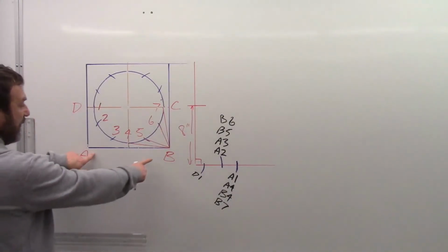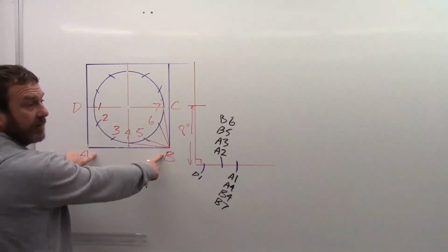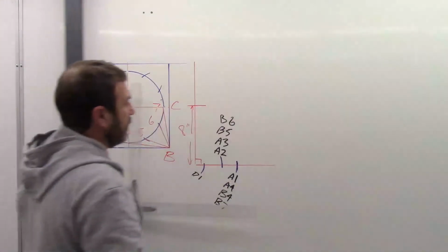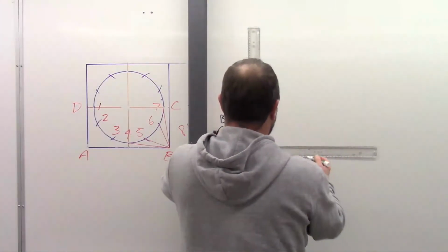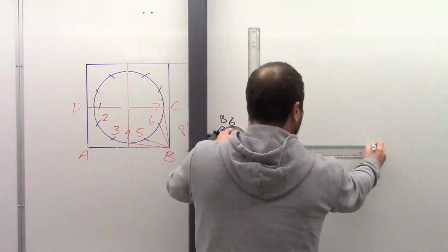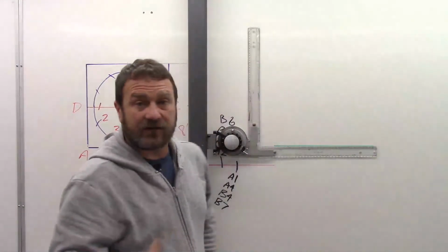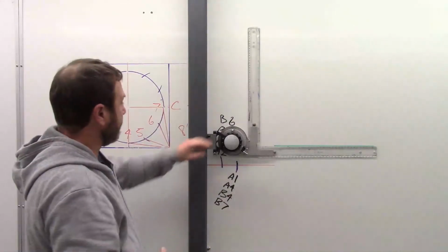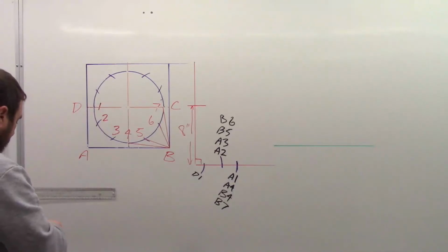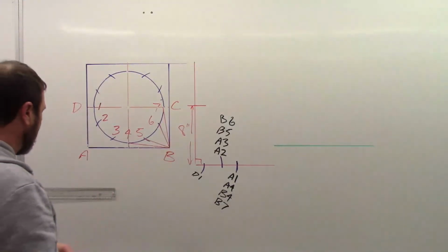Okay, and AB is going to be my starting line, my two known points. Because remember, we define triangulation by taking two known points, creating a third. So I've got a baseline there.